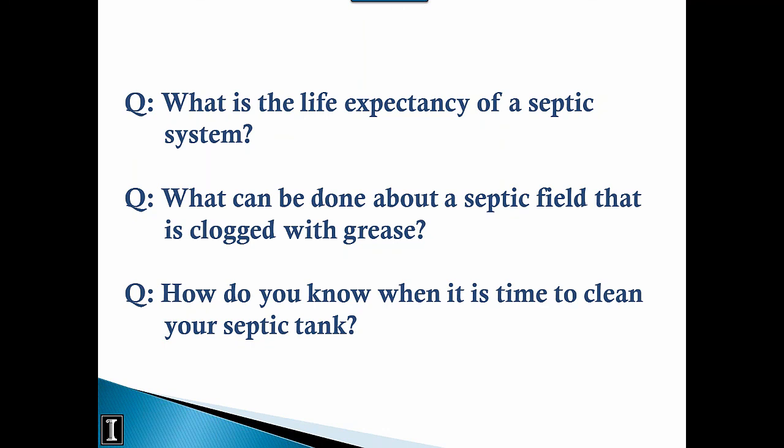Because there are negatives to pumping too much as well, because you're removing all those good bacteria that are breaking down the waste. There will still be a residual there to help reseed, but it takes a while for the septic tank to get those bacteria back to the levels that they were prior to pumping. Another hint might be, if you can, hold off pumping to spring or early summer, as opposed to doing it in the fall if you live in a colder climate, because once again the temperature will impact the bacteria's ability to regenerate itself. In summertime, they'll regenerate a lot quicker.